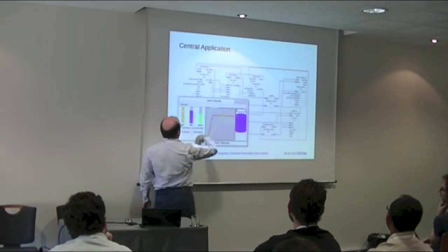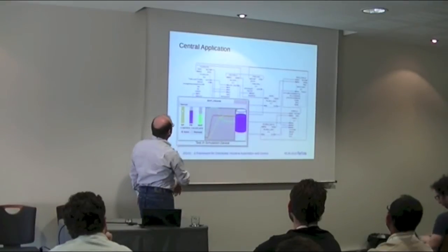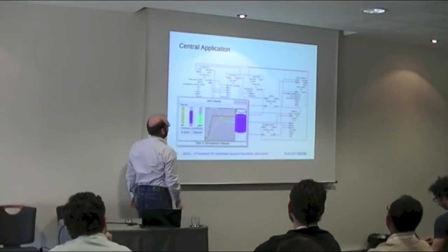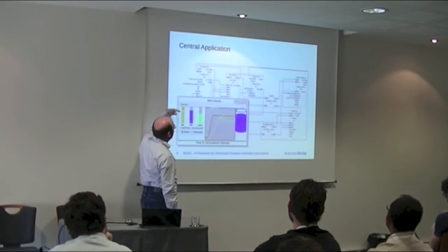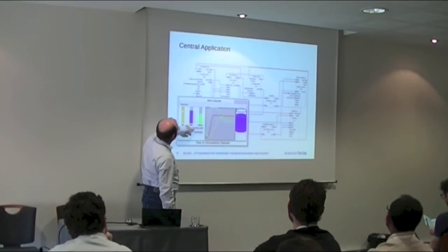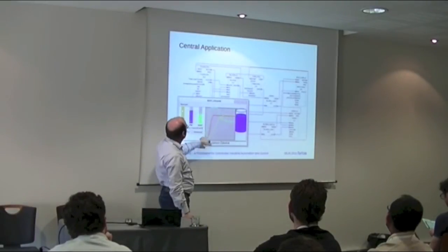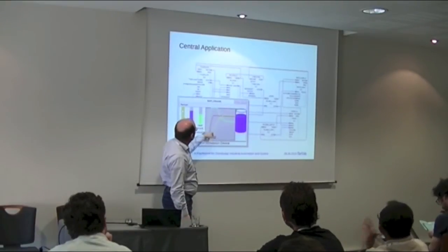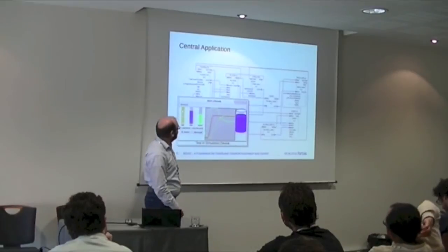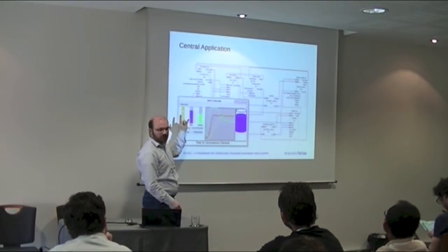So this is the faceplate HMI, so here I can say I want hand or automatic mode, and a set point for which tank level I would like to have. Then this is the current process value of the tank, and this is the output of the valve, so the volume of the valve. And here you see the strip chart, how this will look. The only thing is I forgot to match the colors, sorry for that.